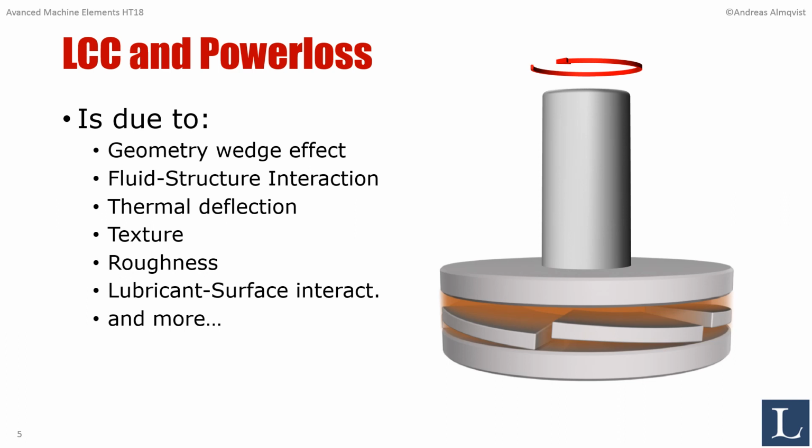There may be thermal deflection, and these can be pretty huge and making the pads convex to the film, and that can cause trouble, can be detrimental in the sense that it generates cavitation on the exit side of the bearing.